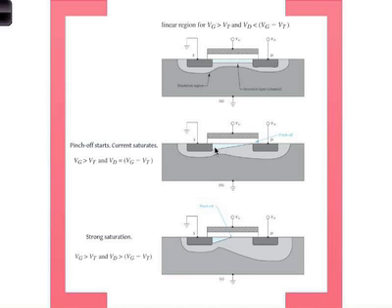The drain to body voltage. I'm talking about just drain to source voltage. The body and the source are grounded, so it's the same. Okay, so you have voltage drop, which happens here, which will basically decrease the electron. So this is positive, right? Remember, this is a reverse bias junction. This is positive, which means that you will deplete the electrons here.